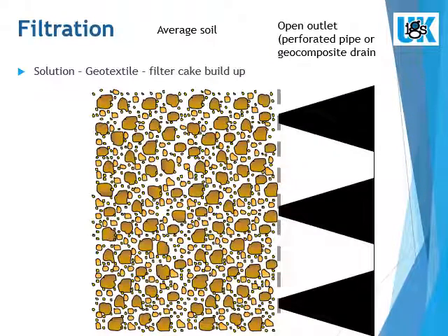Geotextile filters can be carefully designed based on their opening size, defined by testing, and can be matched to any soil, which encourages what is known as a Terzaghi filter to build up at the interface. Let's look at how this works. In the diagram, a filter geotextile, in this instance, is attached to a drainage geocomposite core, leaving free space for the water to drain. The soil is separated by the geotextile, preventing it filling the void in the composite.